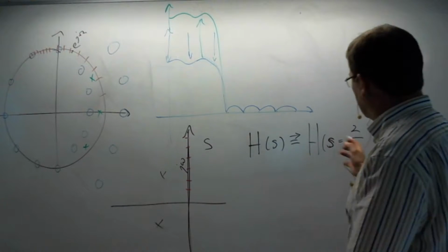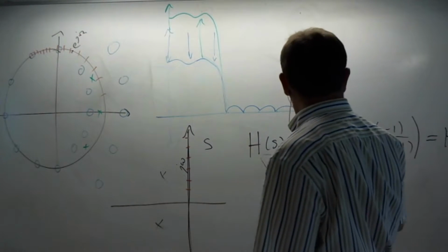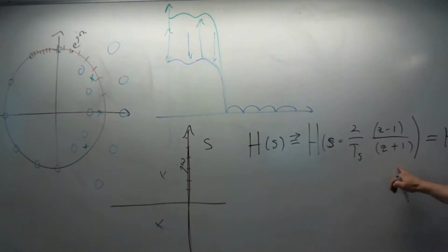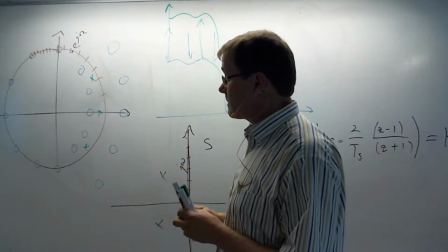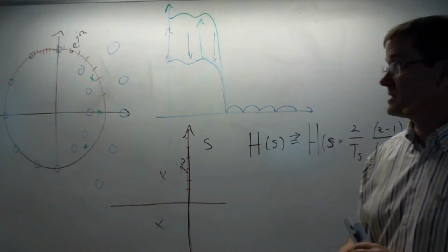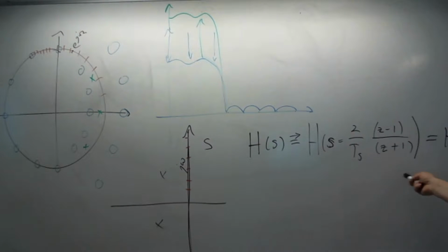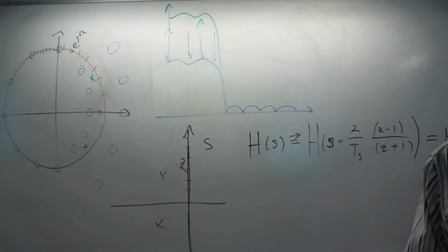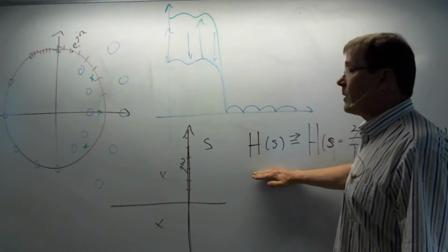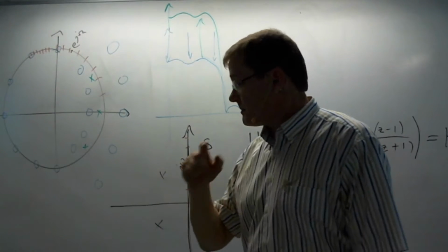Anyhow, if we have a natural system, usually the order numbers are quite small in real natural systems, up to say 8 or something like that. So you easily get an IIR system by using the bilinear transformation. Simple, effective, warps the frequency space. All right, that's one way to basically do the trick.